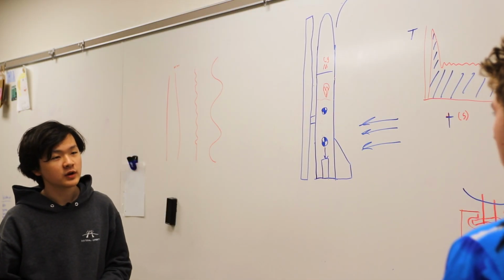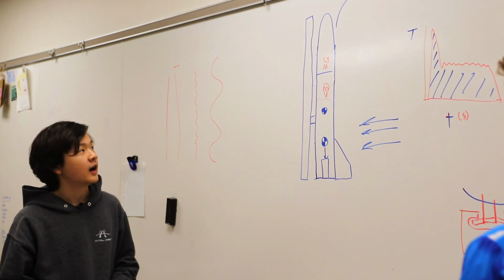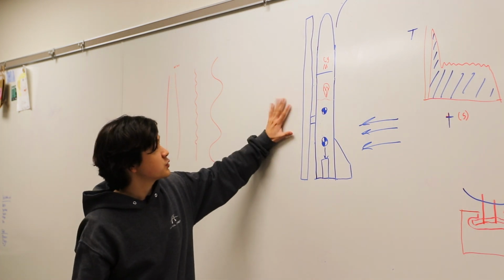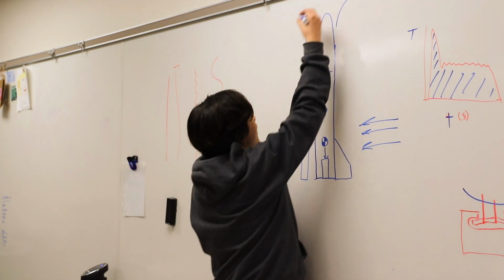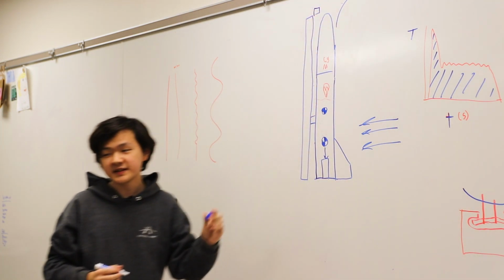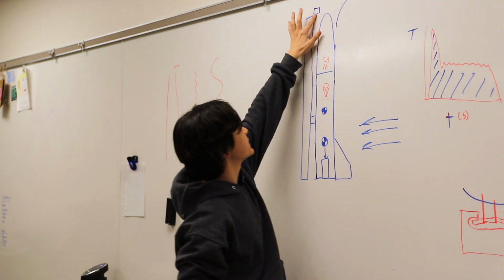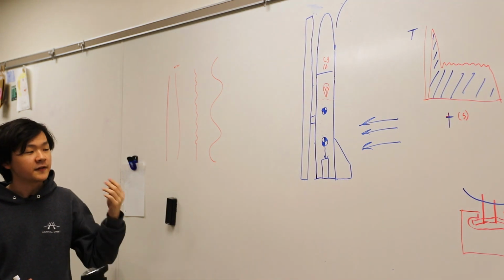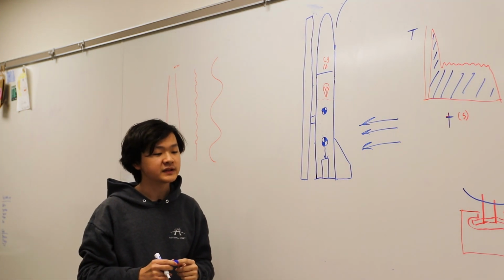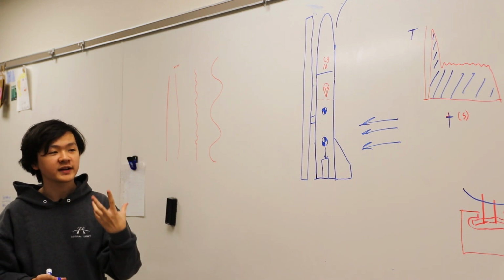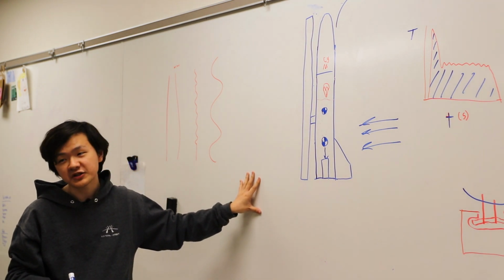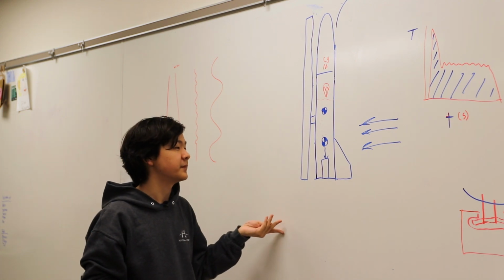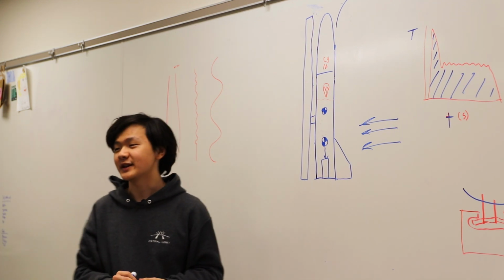One metric that we commonly use is called off-the-rail velocity. Typically, that's the velocity the rocket is going the instant this lug comes off the rail. We call that the off-rail velocity. As he said earlier, the faster you're going, the more chance the rocket has to readjust itself due to pressure from air. And the higher it is, the more stable and straight it will be when it comes off.